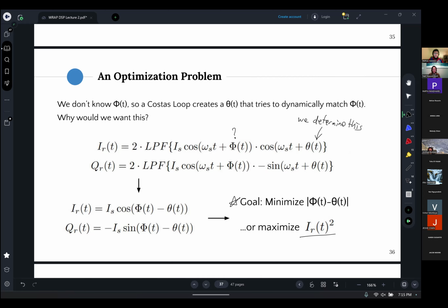Okay, so if we're sticking with BPSK right now, then this method of letting big phi and theta be the same will work because you'll get a cosine of 0. But if you did want to have a Q component that carried some meaning, would this method not work anymore because you would get a sine of 0, so you wouldn't get any information there?